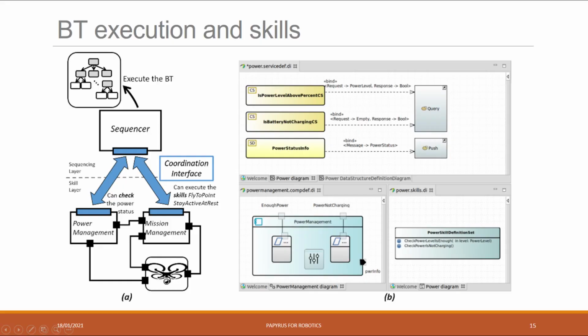And with respect to task planning, it's good to know that Papyrus supports high-level tasks based on a formalism that is known as behavior tree. So you have a hierarchical decomposition of your behavior. You can have some fallback mechanisms or some queries inside this behavior tree execution. And this is particularly well suited for having complex tasks that have to react eventually to some changed environment condition.